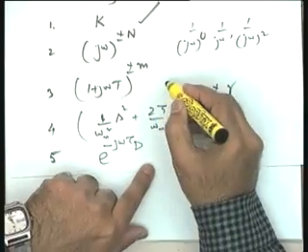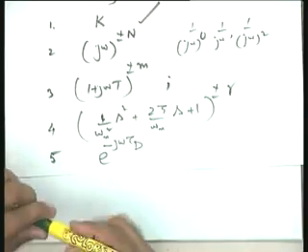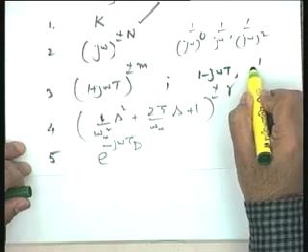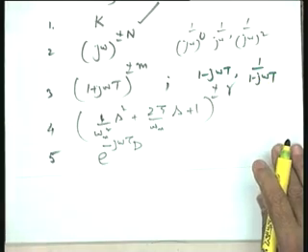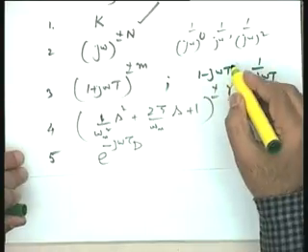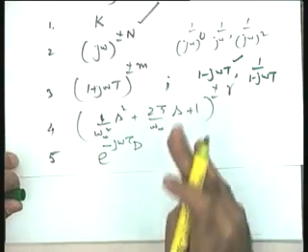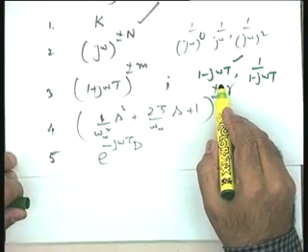One more point please, let me not take a separate building block, let me introduce here itself and tell you that 1 minus j omega T or 1 over 1 minus j omega T is a possibility you cannot rule out. What does this correspond to? This possibility will mean that the zero of the system is in the right half plane. The system is stable, but the zero of the system is in the right half plane.